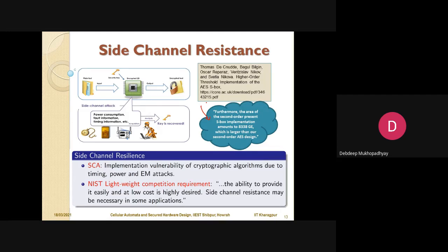What I mean is that suppose you have two designs, an AES design and a lightweight cipher, or LC. With no countermeasure, the LC essentially consumes fewer gates than AES. But when you want side channel protection, you need to protect both, so both will have some extra gates. It may end up that when you finally come up with your protected designs, the protected LC consumes more than the protected AES. In that case, your entire design principle for the lightweight block cipher goes for a toss.